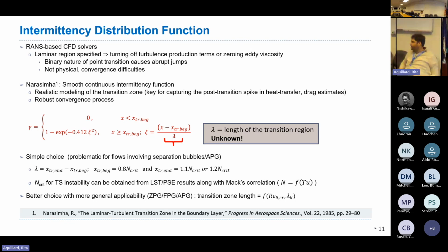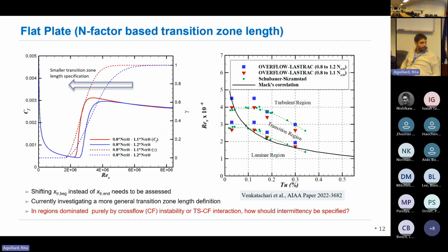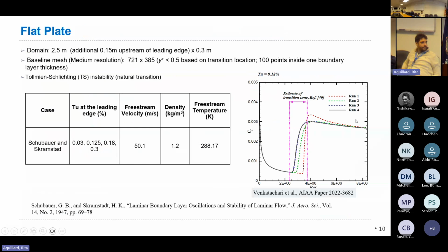Yeah, that's a constant plague for us. People always want to know what the peak heating is, and the peak heating occurs right there. I've spoken to Pedro about it as well. I think Arnal, or one of them, had said that the peak value is essentially, for example, if this is the fully turbulent CF value or CH value, assuming the heat transfer would look the same, you continue this to where the transition onset is. That is the value you would probably hit as the peak, and they try to get that folded back in. But I'm not an expert in that to say whether it's right or wrong. They said that is about the maximum value to hit. I mean, you're in front of the podium, you're more an expert than I am. You're all experts, I guess.